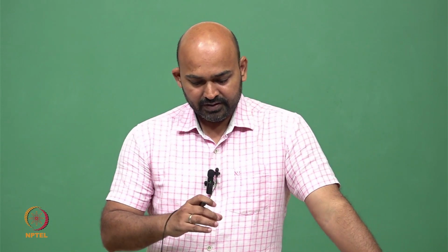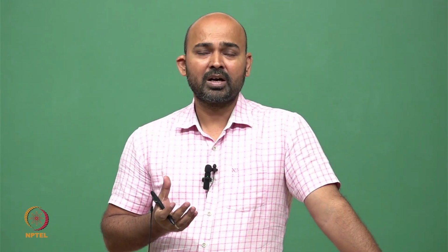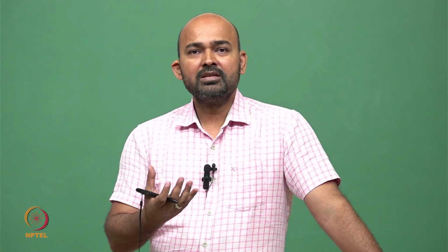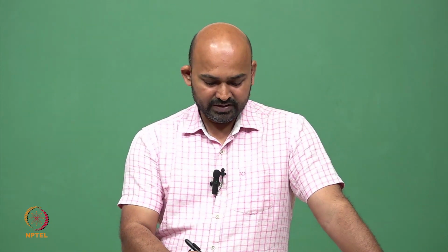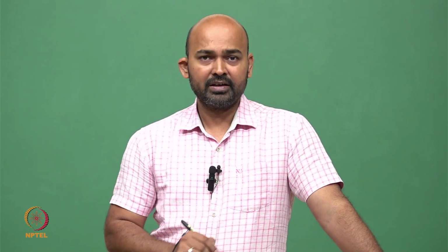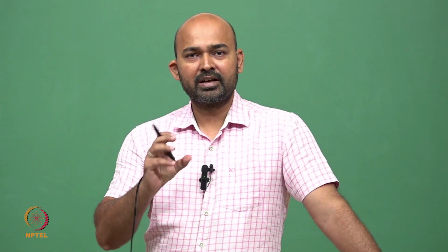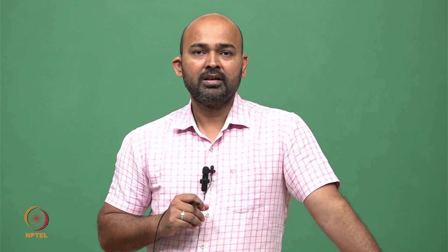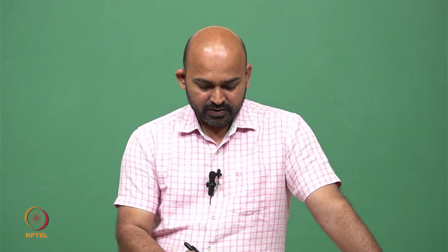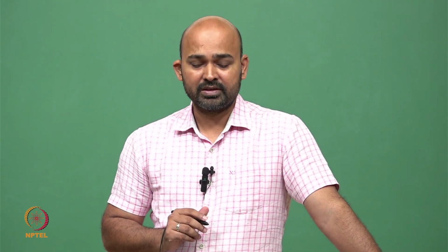So this XL and XC cancel out, leaving only the resistance part, meaning the impedance overall decreases, and because of this decrease in the impedance, we see a sharp increase in the current here. And this sharp increase in the current can be easily detected by electronic circuits which are placed alongside this sensor. So here we have this resonant point and the corresponding resonant frequency.